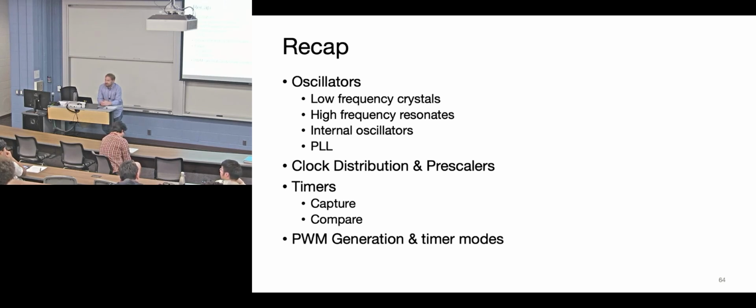Yeah. Can we save power by having less steps, or is there no difference? I don't think there's any difference. What are the things that would care about? Having a module enabled and a timer going. Once it's going, you're burning the power anyways. And so everything after that is just a decision of how you're going to use that data, but the thing's already running. So you would save more power by having one timer going and multiple capture compare registers making decisions on that timer rather than having multiple timer peripherals on and working. That would be a big savings. I say it could be a big savings. I know it will be a savings. I've never gone on a power meter and measured precisely what peripherals consume what power though.